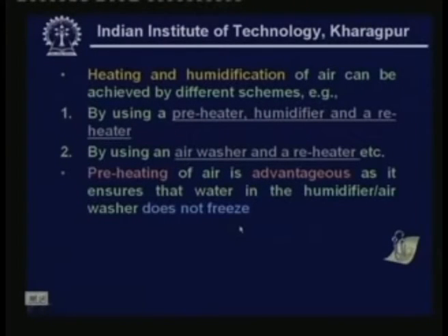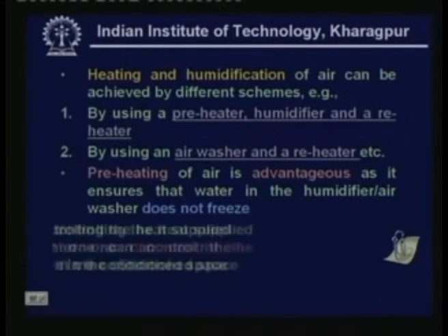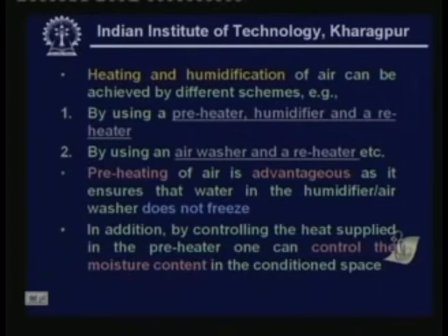Now preheating of course has certain advantages. What are the advantages of preheating? Preheating of air is advantageous as it ensures that water in the humidifier or air washer does not freeze, and in addition, by controlling the heat supplied in the preheater, one can control the moisture content in the conditioned space.